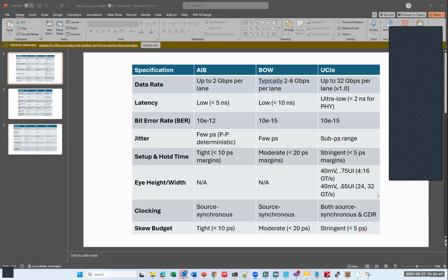And this CDR would typically apply to SerDes type interfaces, right? Would that apply to parallel interfaces as well? Yes, I think it depends on whether a forward clock is there or not, or whether it is part of the CDR circuit on the receiver side. We can discuss this a little bit next time. I want to understand what we need to put in the model that would allow for matching interfaces, right?